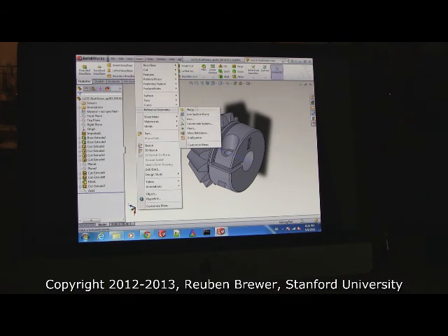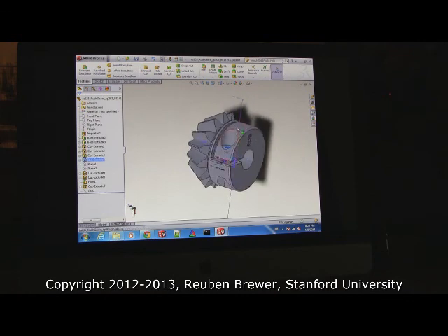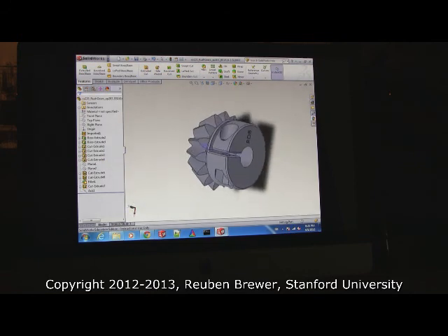So this axis is where we're going to put a shaft. We want this gear to not move along the shaft. So if we put a screw right through that hole, and we put a nut on the other side, then when we tighten that screw, it will clamp onto the shaft, and it will be rigidly attached to the shaft. The reason we're doing that, does anyone know what a set screw is?